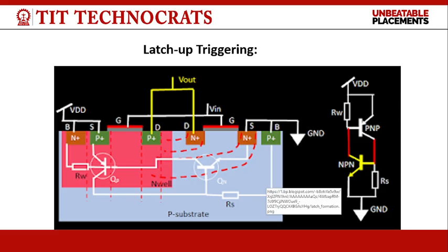Now see, this is the diagram of the CMOS fabrication process. Here we study the diagram of a simple inverter in which we fabricate both NMOS and PMOS transistors. Here a P substrate is used, in which two N layers are formed to form the NMOS, and an NWell is formed in which two P diffusions are fabricated, which forms the PMOS transistor. Both NMOS and PMOS transistors can be formed using this NWell as well as the PWell process.